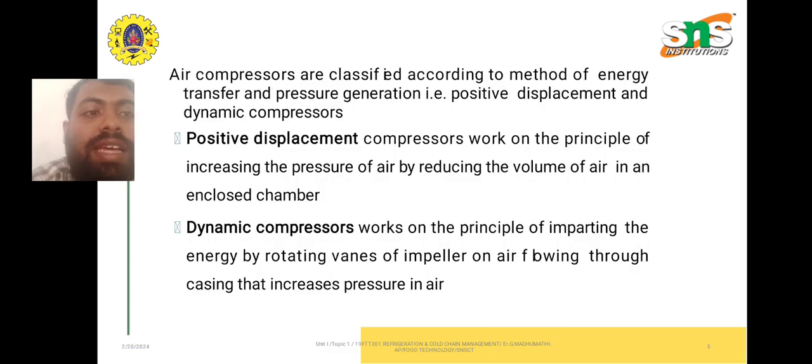Air compressors are classified according to the energy transfer and pressure gradation. First is positive displacement. These compressors work on the principle of increasing the pressure of air by reducing the volume of air in an enclosed chamber. Dynamic compressors work on the principle of imparting energy by rotating the vanes of an impeller on air flowing through a casing, which increases the pressure of the air.